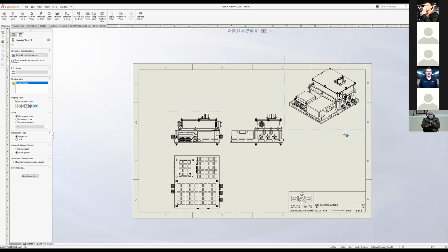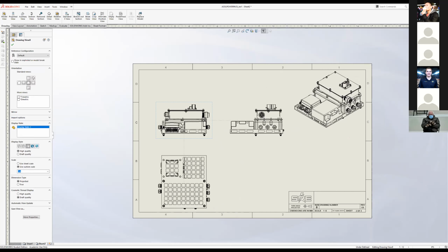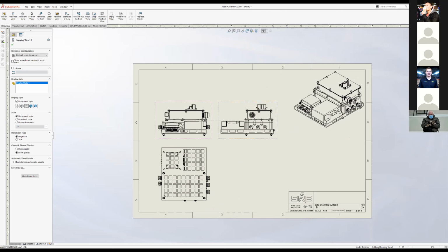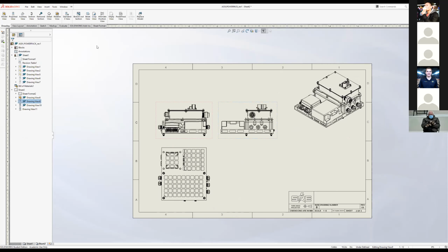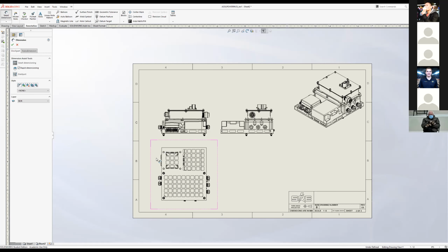And then sometimes you'll see drawings where these parts are specifically from another supplier, and the assembly drawing is just putting the parts together. And so sometimes you'll have source controlled drawings, which basically means you're making a drawing for your internal use, to say that we're purchasing this part from this certain supplier only, because they've done the testing that you need it to have done, or they've just made reliable parts or something.